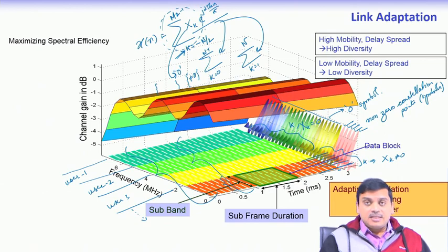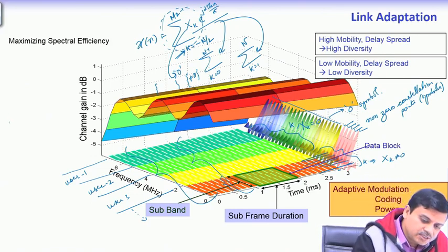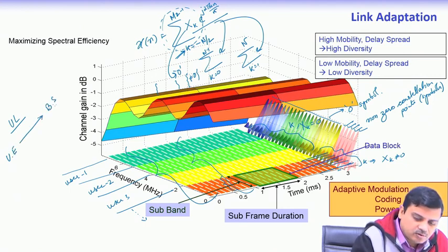So, the base station suffers a PAPR problem, but we have discussed in the previous class that in the uplink direction the PAPR problem is addressed in LTE, whereas in the downlink it is not addressed. The main reason we have said is that the uplink is from the user equipment to the base station, which is also known as the E node B.